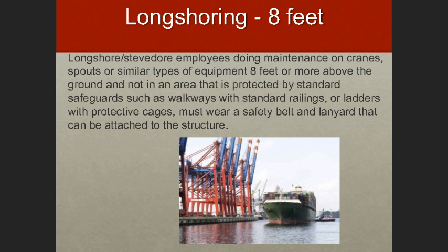In longshoring and stevedoring, again going back to the maritime OSHA regulations, we have an 8-foot standard. So longshoring or stevedoring requires maintenance on cranes or spouts or similar types of equipment. We have an 8-foot fall protection standard there whenever an employee can fall at that distance or greater. And so typically we like to see a full body harness there and some type of lanyard attached to the structure or to some other anchor point.